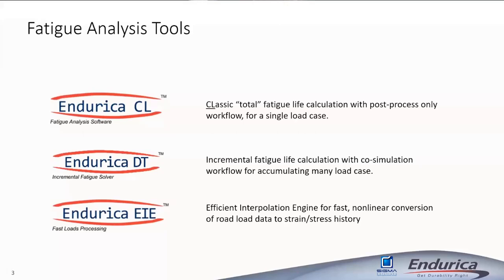The final tool is what we call Endurica EIE. That's an acronym that stands for Efficient Interpolation Engine. The reason you need EIE is because sometimes you're in a situation where it's important to be able to calculate fatigue under the action of road load data, right? You go to the track, you make a recording at say 1,000 hertz on your data acquisition system, and you come back with a history that's maybe 2 million time steps long.